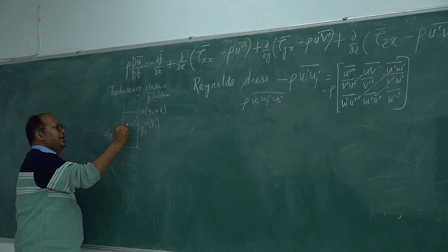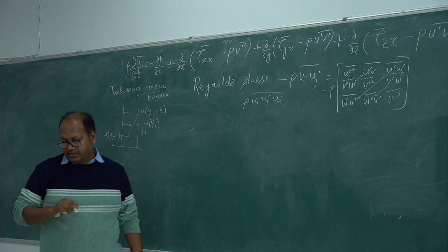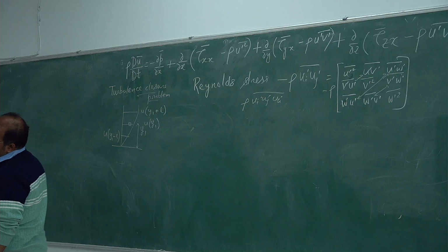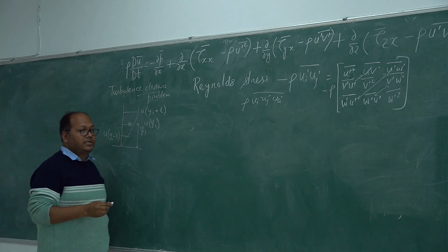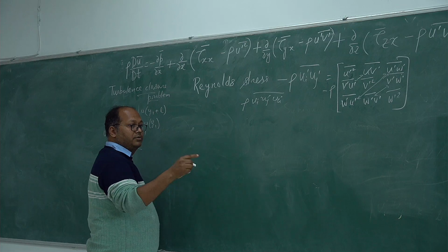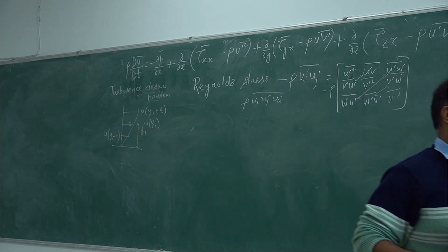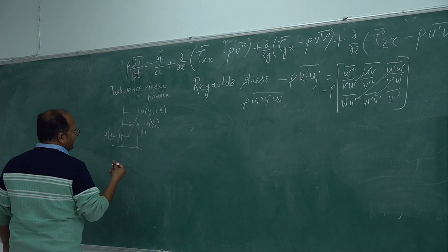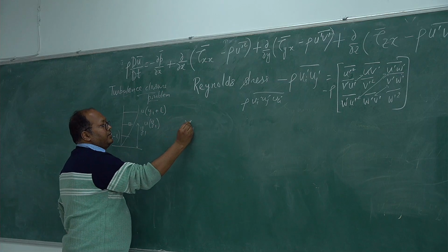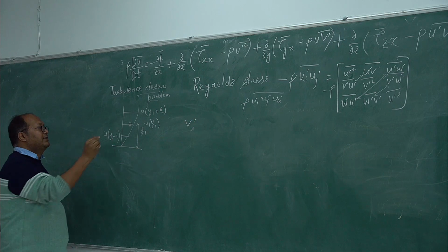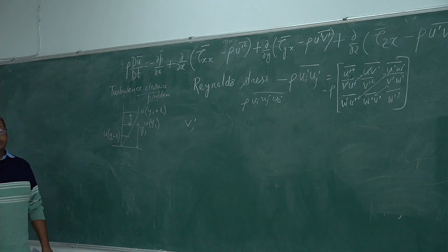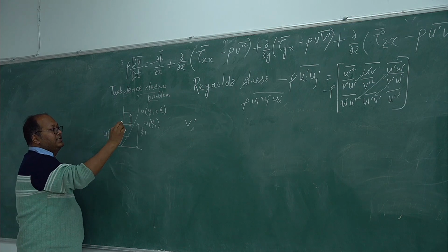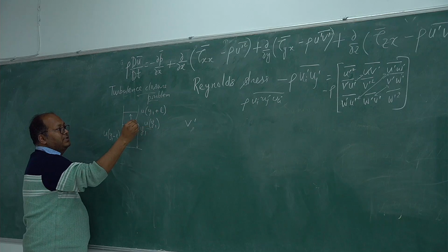So now let's imagine there's a fluid element here in the intermediate flow, and let's say there is a positive velocity fluctuation, which implies that the fluid element will basically go to the upper portion. So when this fluid element goes to the upper portion, essentially this fluid element with its lower u velocity mixes here.